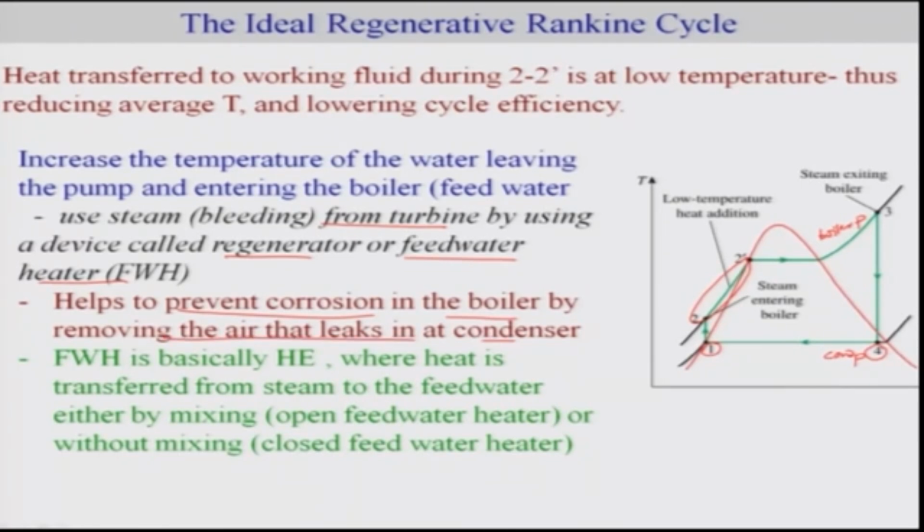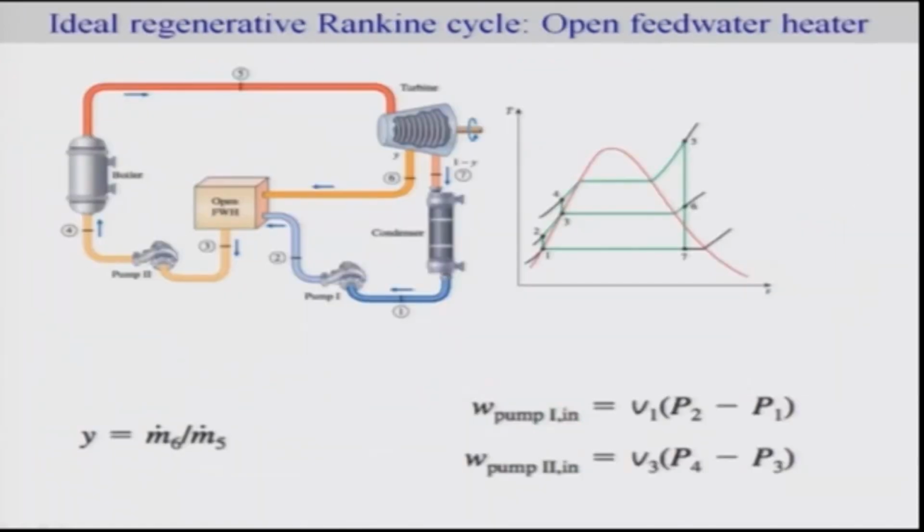So what are the different forms of feed water heater, which is nothing but a basic heat exchanger? You can have direct mixing, which we call an open feed water heater, or closed feed water heater, which is without mixing. Let me first describe the open feed water heater. This is the overall process for what we call the regenerative Rankine cycle, where we are going to use an open feed water heater. Let's look at the complete process here.